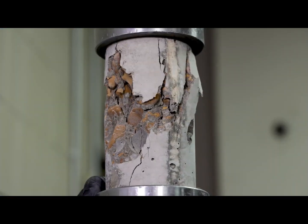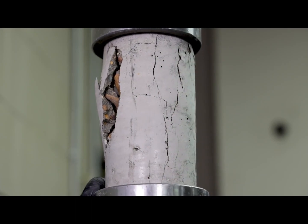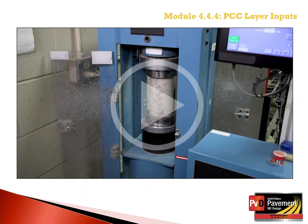As noted in the previous presentation, many agencies specify the minimum compressive strength of the PCC mixture. As we noted earlier, the compressive strength is used to then calculate the modulus of rupture, which is directly used to predict performance and the different distresses in the PMED software.